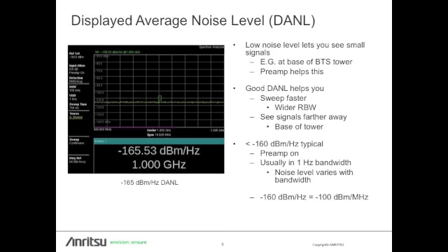And the reason: minus 160 dBm sounds like a very, very low level, but when you translate that to dBm per megahertz, like a whole channel somewhere, that's only minus 100 dBm. That's pretty close to the sensitivity of many phones. So that's why we need to have good sensitivity there.